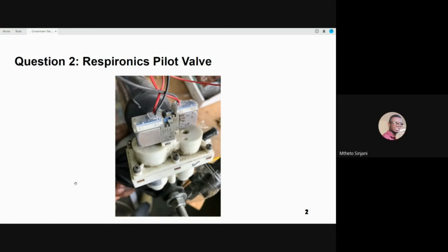So if the pressure you're getting is lower than the recommended, you will need to service the compressor. On this one, you have to have the right caps and the sleeves for this model. When you're done with servicing, you can check the performance again.